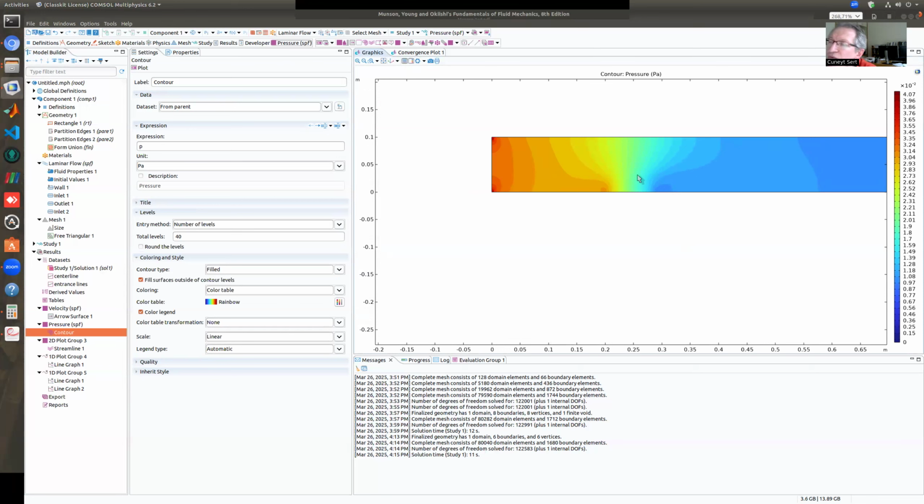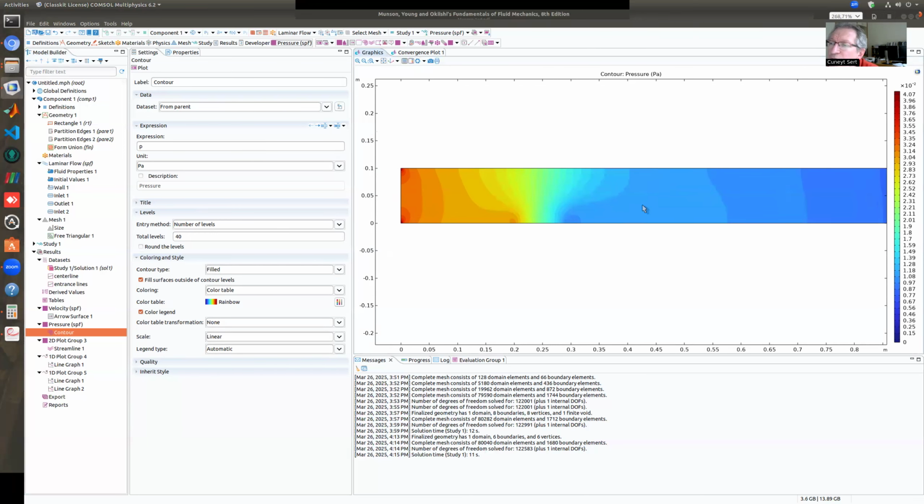Do we have an analytical solution for this one? Obviously, no. Nobody knows an analytical solution for this flow. That doesn't exist. Is this correct? I don't know. I have to do it carefully. Maybe I have to use a couple of different meshes. I have to be careful in every step. When you do a quick solution like this, you can generate these nice looking contour plots, colorful plots, but they can be wrong. They can be wrong. So in order to make sure that they are correct, you have to really be careful at every step, not like we're doing it today, right?